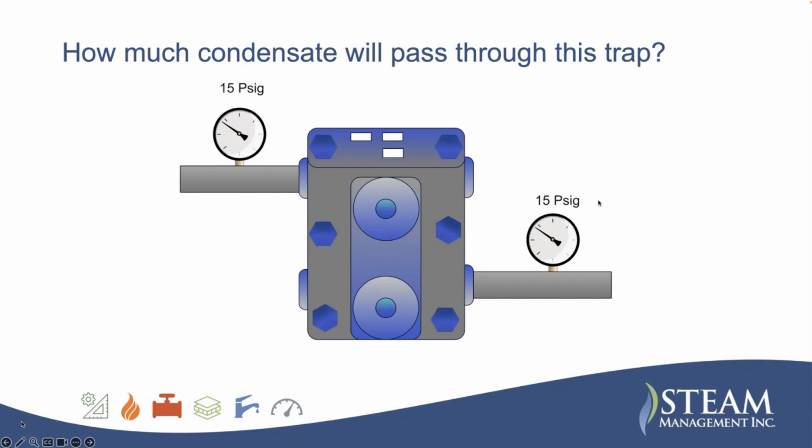And how would I get 15 psi on the outlet? Let's say the steam trap is bad on the next item down or the next room down. It's leaking steam into here. It could pressurize this condensate line. So you go in here thinking, oh my gosh, we've got to change this trap out, or change this valve out or something. And every time you do it, it doesn't do any good. It's because the steam trap is failing on the other one. So when I talked about the solution and the problem are rarely in the same room, this is what I meant by that.